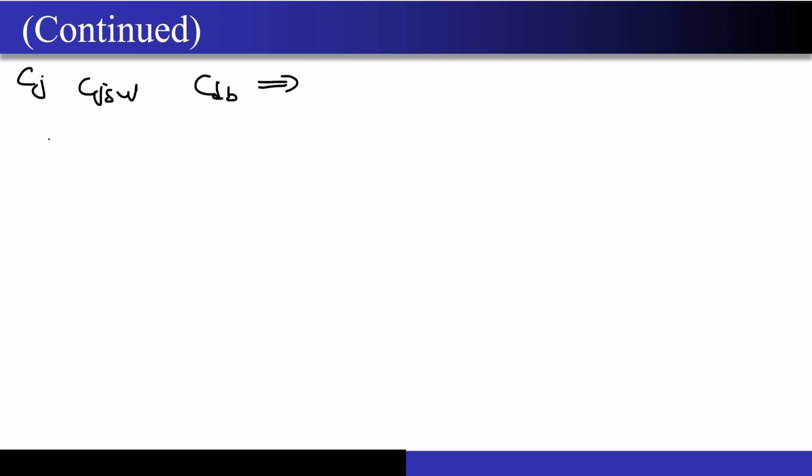So now one hack I would like to tell you that came from experience is basically, if you are designing the circuits in minimum channel length, this will not directly apply if your transistor is having, let's say, 540 nanometer channel length or something. But if you are designing RF circuits or circuits having the minimum channel length of that particular PDK, right, then you can note down these values. This comes from experience of looking at the Cadence tool extensively for many years.